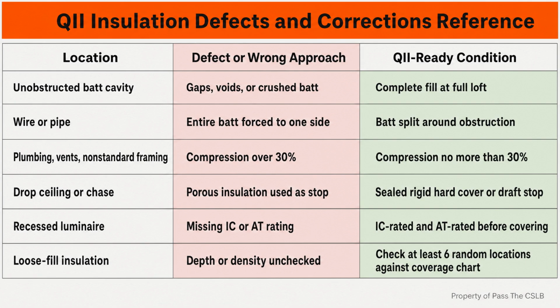Worker protection is a separate obligation from thermal performance. Spray polyurethane foam can expose workers to hazardous chemicals, including isocyanates. When an employer uses tight-fitting respirators for hazardous insulation work, California respiratory protection rules require a written, worksite-specific program. The program includes administration, medical evaluation before fit testing, and appropriate respirator selection and use. Buying masks at a store does not create that program.